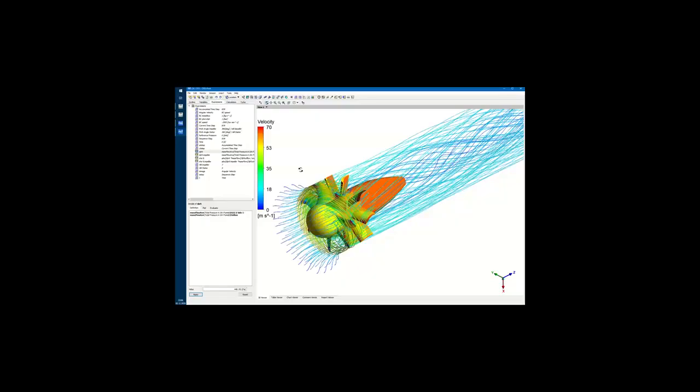Is there anything you would like to add, Sasha? No, that's all. I think that was a very good explanation. I have to admit there are no problems with small features. It all depends on the meshing tool. Small features with TurboGrid are not a problem, and small features inside of Ansys meshing depend mainly on your mesh settings and how far you are willing or need to refine in order to achieve a mesh independent result. Okay. And last question. Thanks.